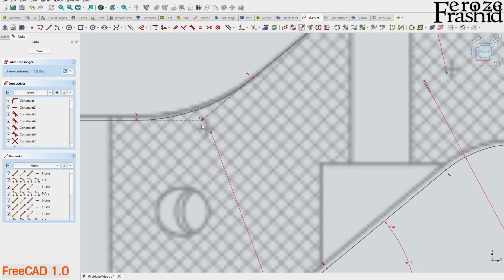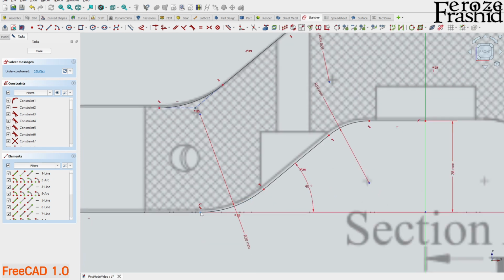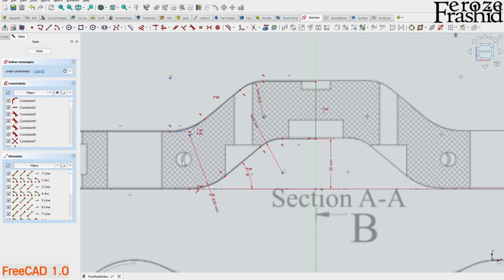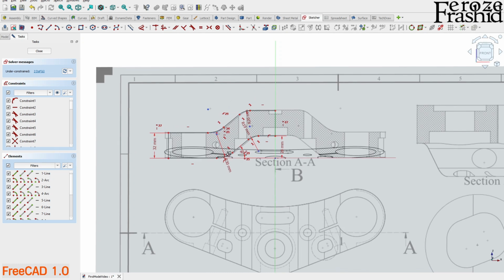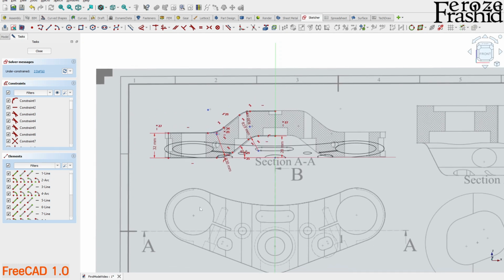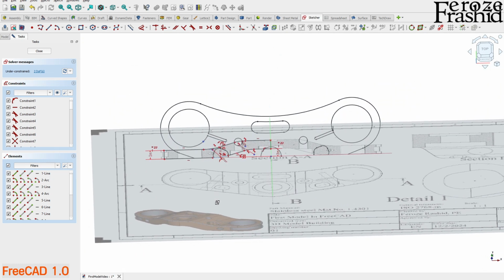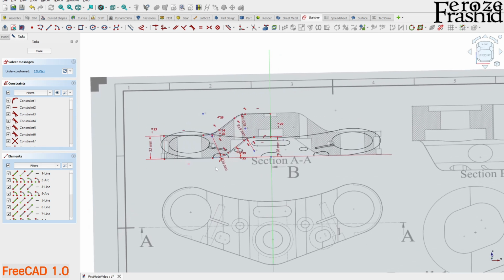Now this apex, this meeting point, take this point with this horizontal meeting point on the horizontal arc and make them vertical, B on the keyboard. So that kind of places them at the same vertical plane. So we have 2 degrees of freedom left, which are the length of this whole object. And we can take help from the previous sketch that we built, or we can just calculate those. So I would like to keep them independent as much as we can.